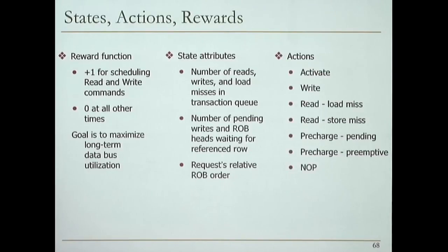And actions, these are some actions. Activate, clearly, things that we've discussed so far, but we actually distinguished between a load miss read and a store miss read, and a preemptive precharge. Remember, you can have a preemptive precharge as opposed to a precharge to a particular pending row that has a request to it. And a no-op. Actually, no-op could be an action too. Sometimes you may decide not to do anything, right?